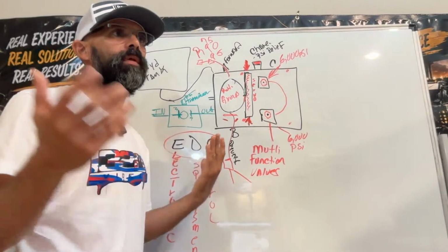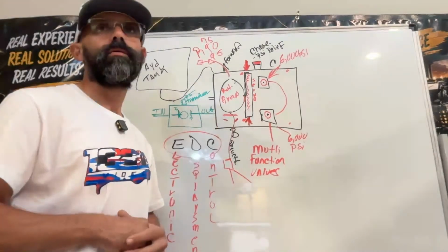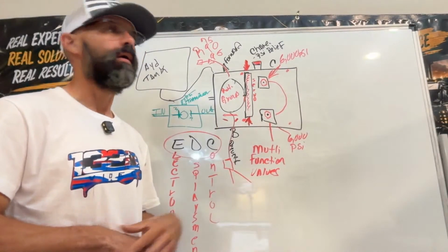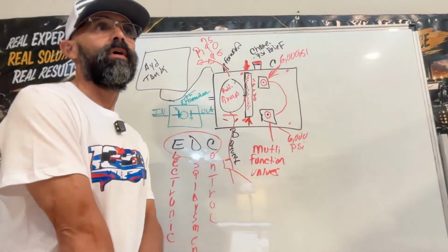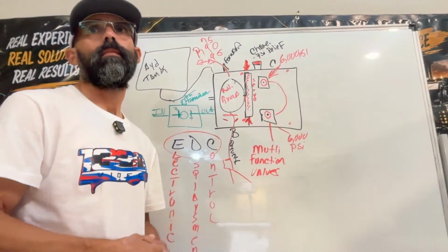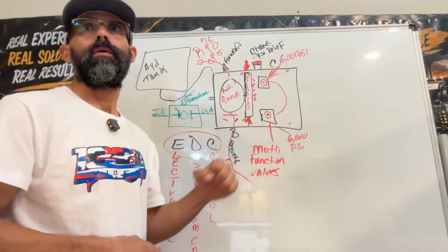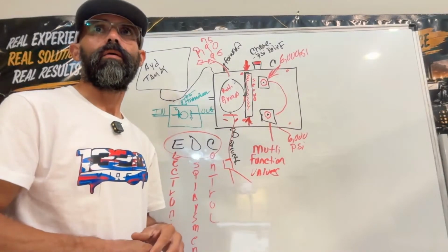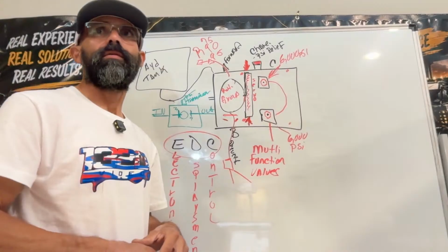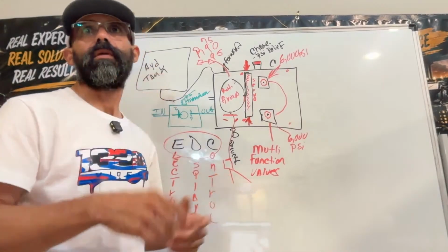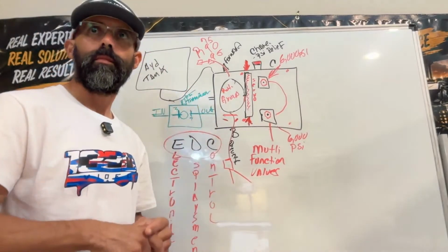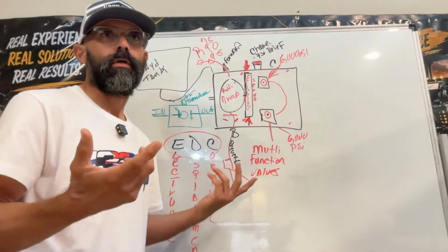You might say, my pressure gauge only reaches 3,000 psi, and this system puts out 5,000. I don't recommend putting a 3,000 psi gauge on a 5,000 psi system, because you're going to damage the gauge, and then you can get hurt.